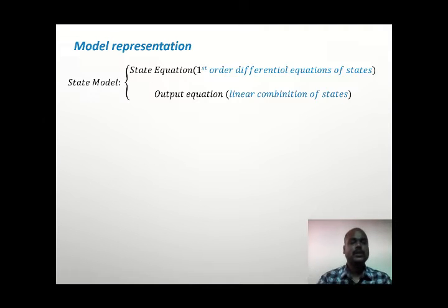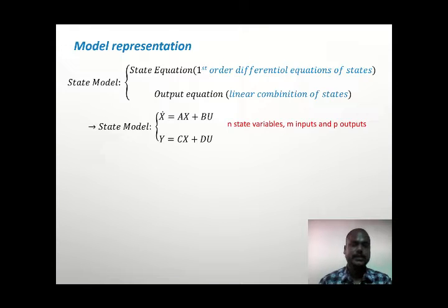So what is a state model? State model representation is a combination of two equations, the state equation and the output equation. The state equation is a first order derivative equation, x dot equals Ax plus Bu, and the output is y equals Cx plus Du.